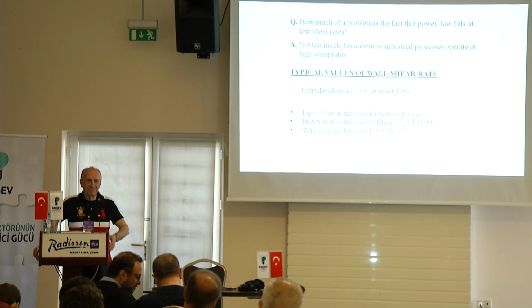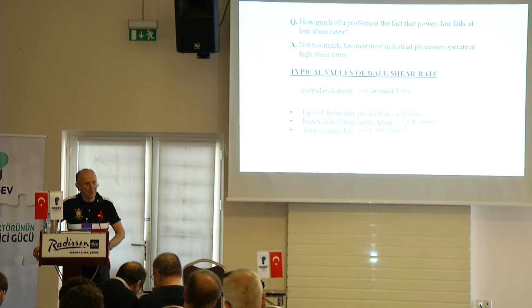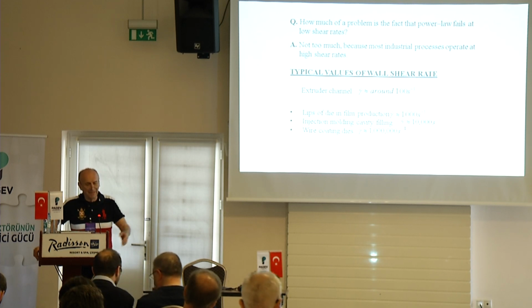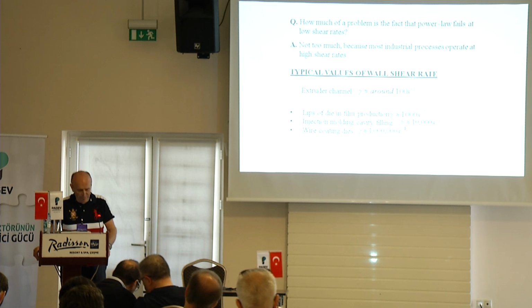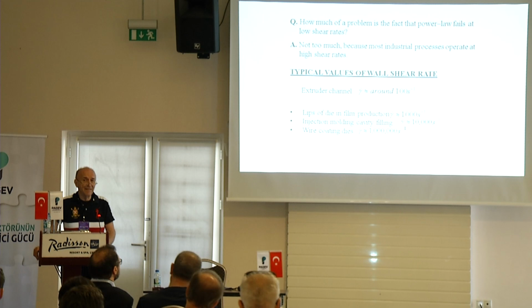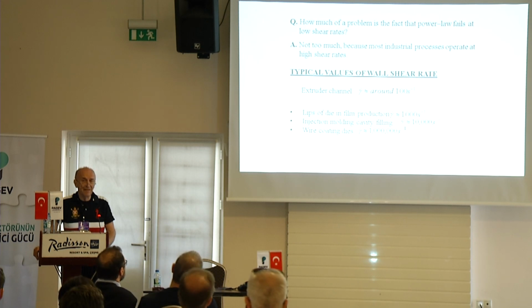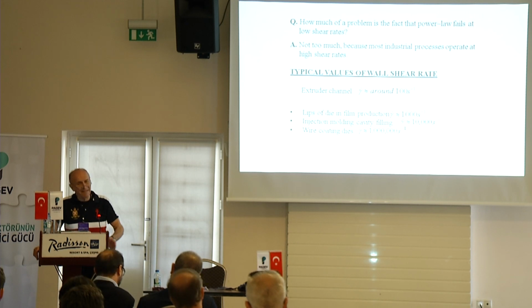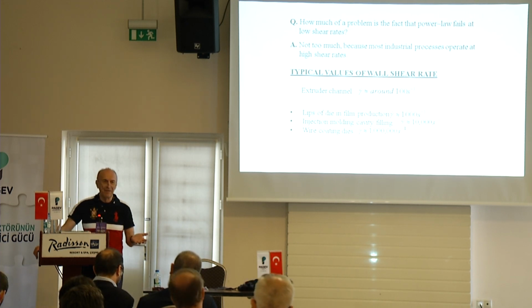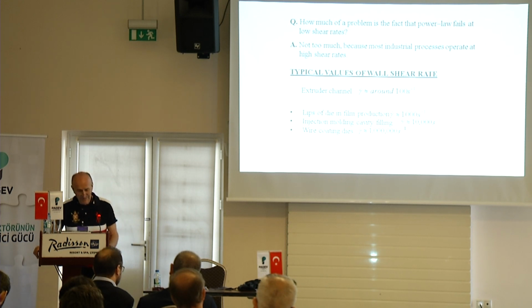I'm sure there are several people from packaging applications, film production, and in the die lips, the shear rate will probably reach 1,000 or maybe 2,000 or so reciprocal seconds.